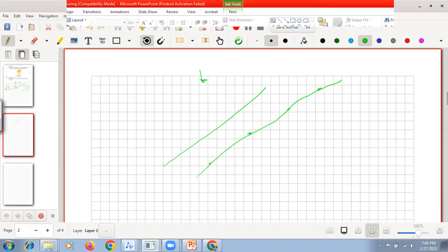If you see from the top, the spacing of the contour lines will be equal, perfectly equal. That means it is a uniform slope, because this contour interval is always uniform, say 1 meter. And as this is uniform, these horizontal lines have to be equally spaced. So when you see a contour pattern like this in the plan, that means it has a uniform slope either in this direction or in this direction.